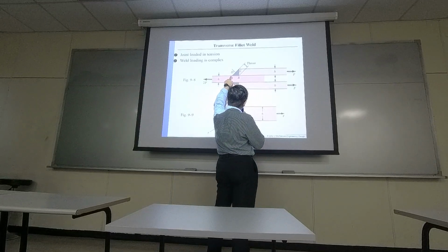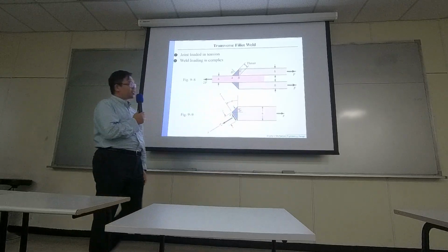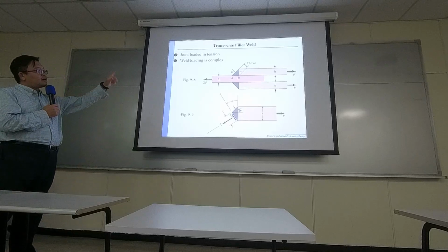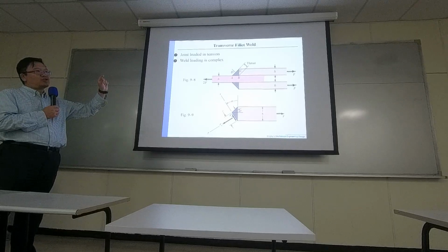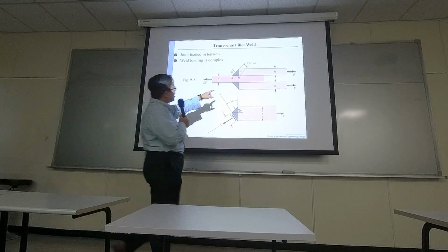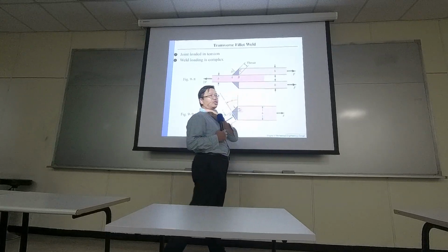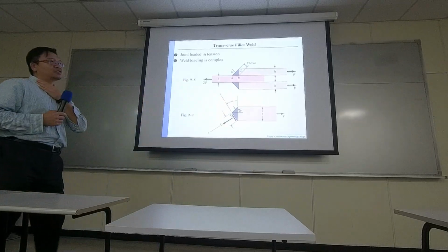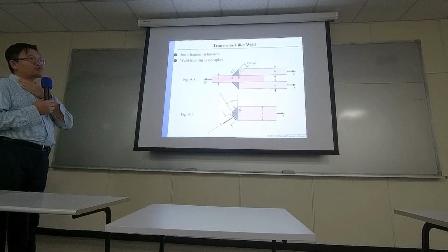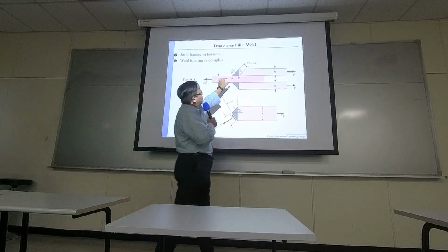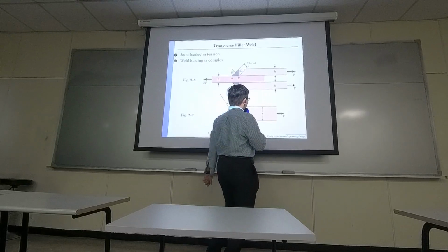What's happening is, in this particular case, when you observe its geometry, you usually see the width AB, or width BC. But in reality, the material has a narrower neck right at B and D, right here. So we call this throat, like your neck. So the stress area needs to be computed by the width of the throat, not the width right here, AB or BC. Okay?